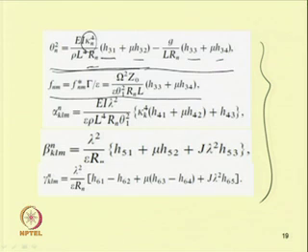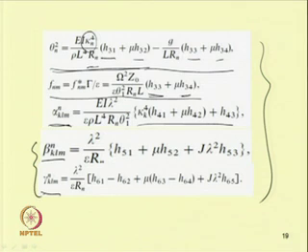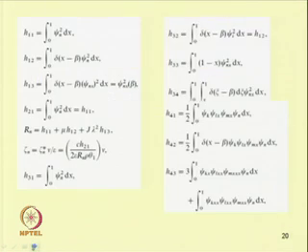The forcing term contains the frequency of the forcing, the amplitude of the forcing, then the fast mode frequency, and H33 and H34 are the integral terms, which are defined after this slide. This is the nonlinear term alpha_nklm, and this is beta_klm and gamma_klm. Beta and gamma are the nonlinear inertia terms, and this is the coefficient of the cubic geometric nonlinearity.